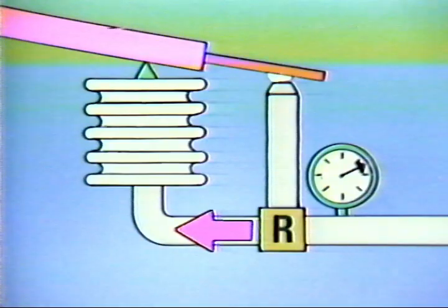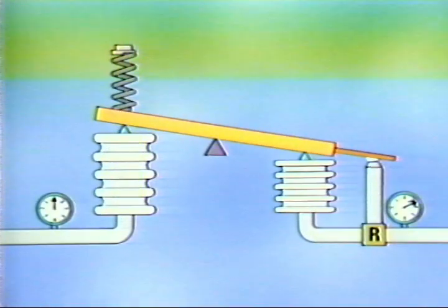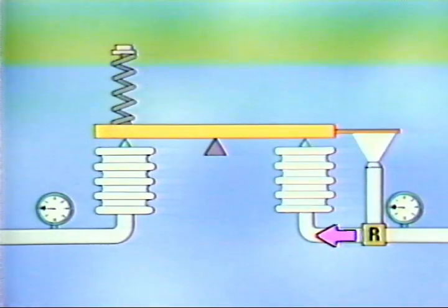For one, it's fed to the output balancing mechanism, another bellows, which we'll call a feedback bellows. If input changes, the new output causes the feedback bellows to bring the controller back into balance. The output signal is also sent to position a final control element. This is the corrective function of the controller. Right now, the controller is in balance, with its output proportional to its input.